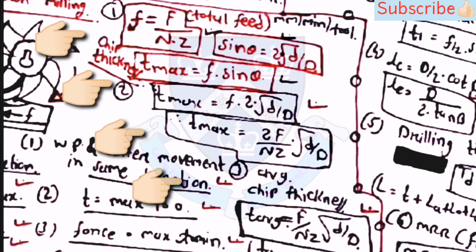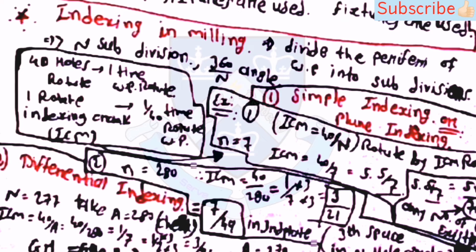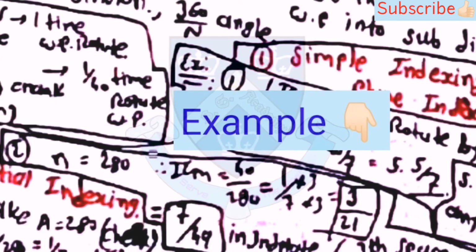Then the third one is average chip thickness. T average is equal to F upon (N Z) into under root d by D. So T average is also equal to T max by 2. Then indexing in milling can be achieved by dividing the periphery of the workpiece into subdivisions, where n subdivisions are there. Then 360 upon n is equal to the angle. And suppose 40 holes are there, then for each hole the workpiece will rotate one time.